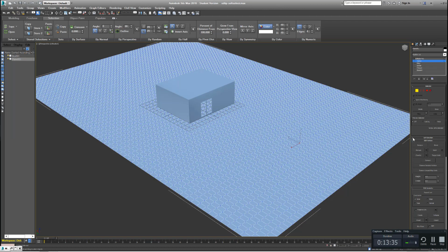What I really want to do is expand this soft selection rollout. You can find it within your Modify tab, and it's right below the sub-object selection. It's sometimes a little bit hard to see. You actually have to hit the plus sign, and you want to click Use Soft Selection. And what you see is the minute I did that, my singular red point, my red vertices, has gotten this sort of halo around it. And that's great. That's exactly what I want.